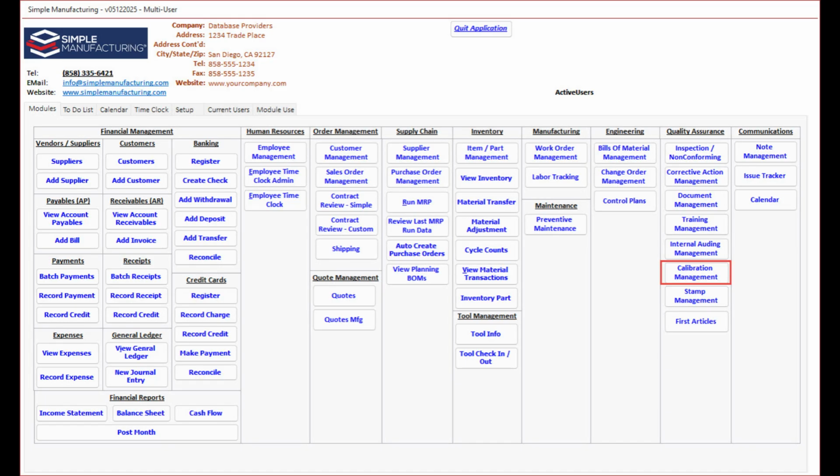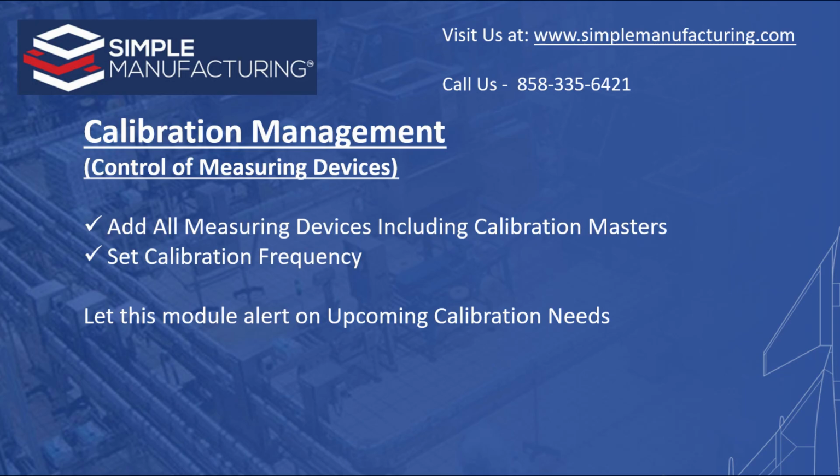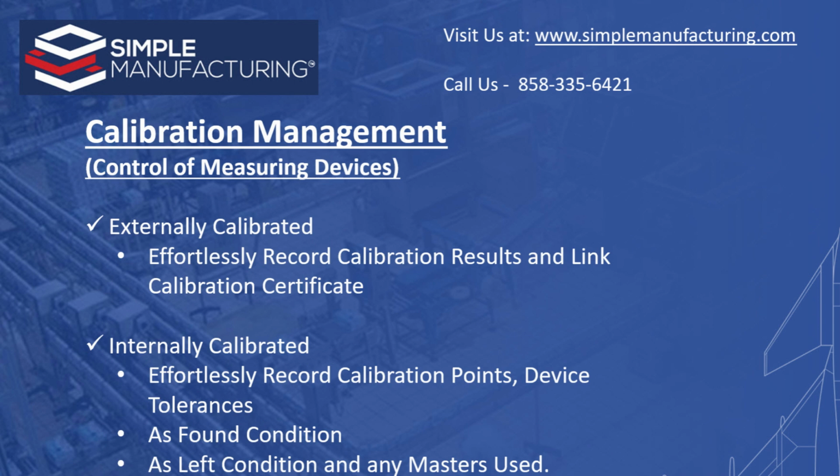Moving on to calibration management. Every manufacturing business has some form of measuring devices that require regular calibration. Managing those devices and calibration masters is simple with this module. Add all of the measuring devices, set the calibration frequency, and let our module alert you when devices are due for calibration. When calibration of those devices is performed by an outside agency, easily record the calibration results and link the calibration certificate for effortless future retrieval. When internally calibrated, effortlessly record the calibration points and tolerances, the as-found condition, and the as-left or as-adjusted condition.